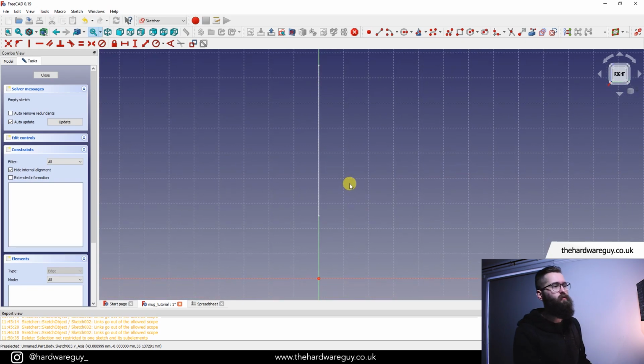And we're going to use these as a reference here to create the handle thickness, right? Because we're going to use this sketch and use a tool called the sweep tool to sweep this sketch along that arc to create the handle, which is a really great tool and I think you'll appreciate it.